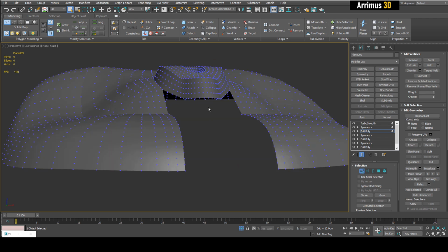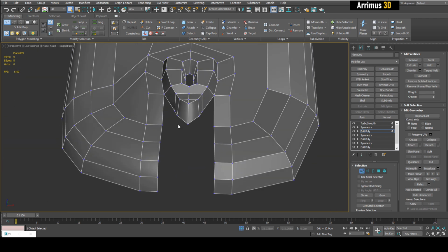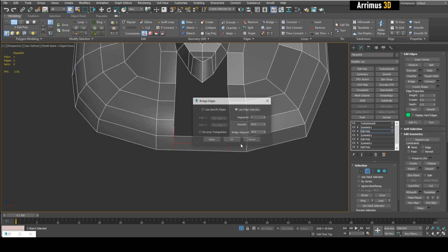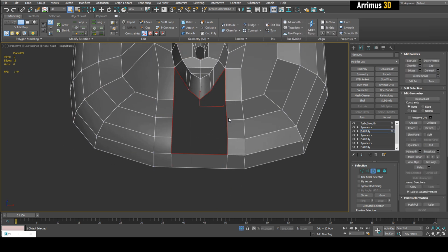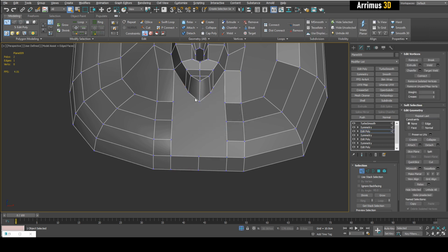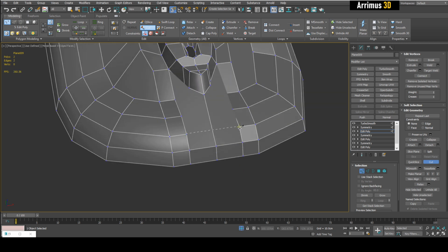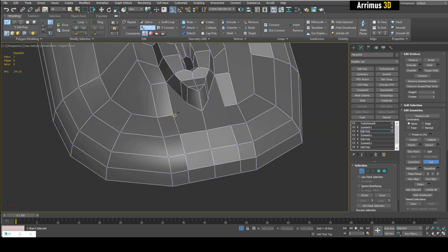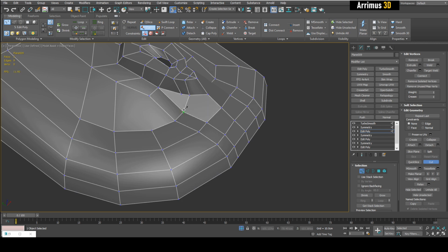All right, now for example, if I'm ready, I can fill this area in. So what I would do here is bridge these two edges, border, cap this, and then simply connect the vertices, as well as cutting with snap on. Pressing S to activate snaps, right clicking here, making sure it's set to vertex, and then we can just kind of make sense of this.